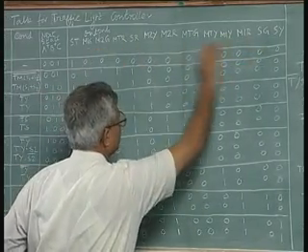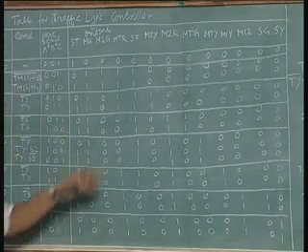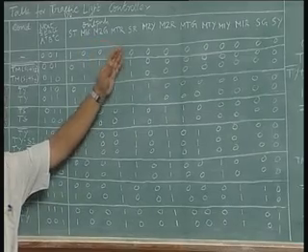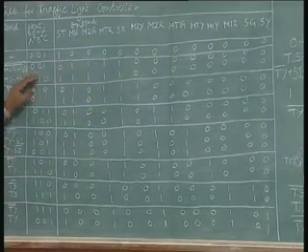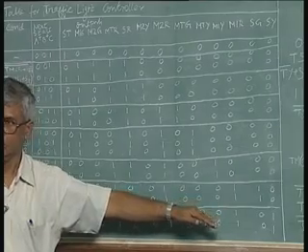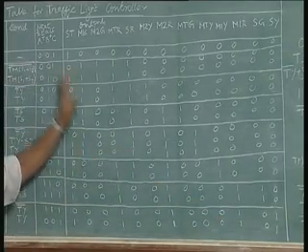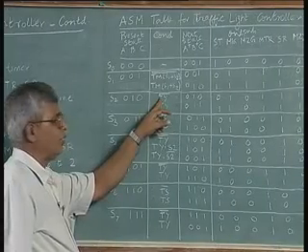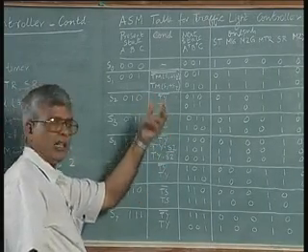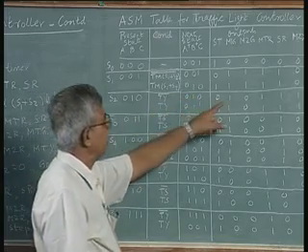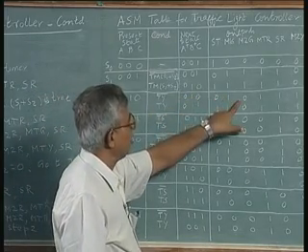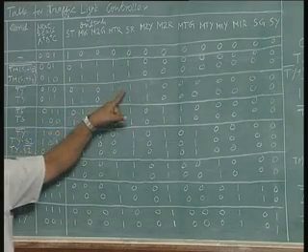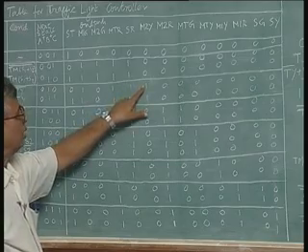The reason it is written in a random order, we would normally like to see M1G, M1 yellow, M1R, M2G, M2 yellow, M2R. That is one way of writing. This way has been written in the order in which they appear in the ASM chart. The order in which these outputs appear in the ASM, we have put in that order. So as corresponding to the state of 0 1 0, you are waiting for the yellow time to be over. As long as the yellow time is not over, you continue in the same state, keeping the main one green, main 2, main turn red, side red, M2 is in yellow state, all others are zeros.